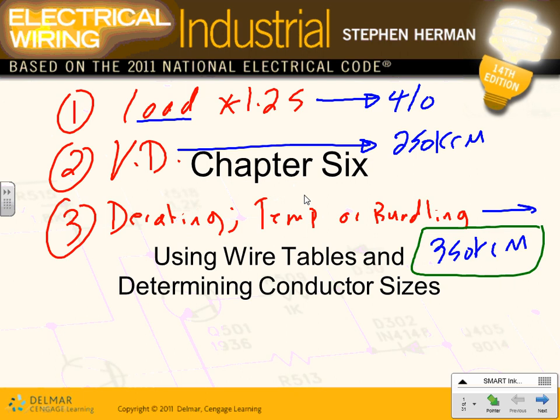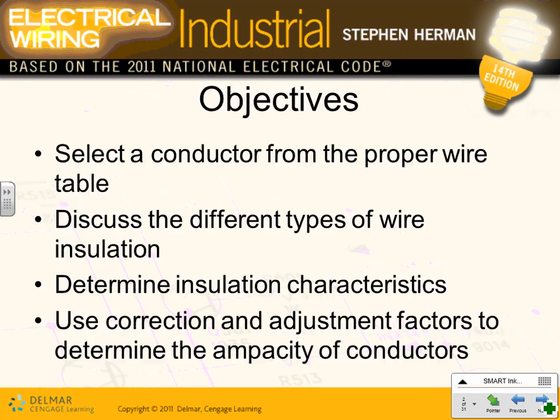So remember that. Most of the stuff we did, guys, was on calculation. We did the derating before. So if you come up with a number higher than what the code requires, you're going to go with the derating. If you did voltage drop 250, you're going to choose the largest size. That's it when it comes to the calculation. Can I have a thumbs up, chat? We understand you have to use the largest size. Okay, when you do the calculation, you have to use the largest size.